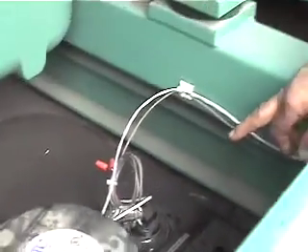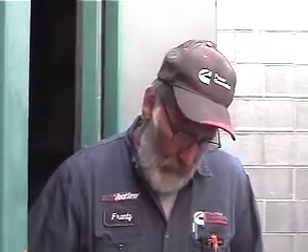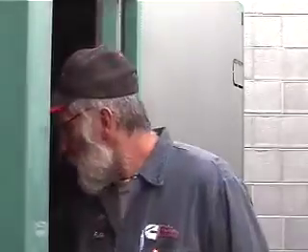And if you look right here, there are some alarm wires. This particular one here is the low fuel alarm. So if you get to somewhere around a half a tank, that's going to go off and give an alarm saying that we have low fuel. The rupture basin alarm is a separate alarm, which comes in from the back. It's hard to find and see. That will tell you if you have fuel in the secondary containment area.